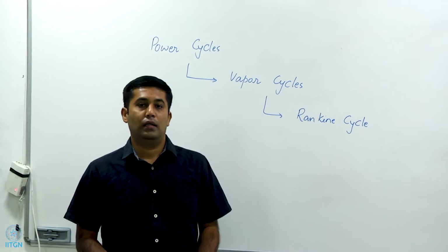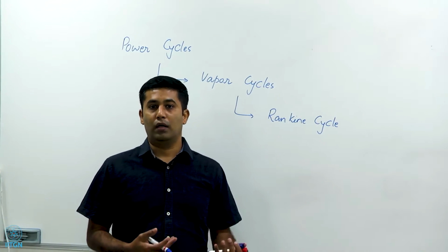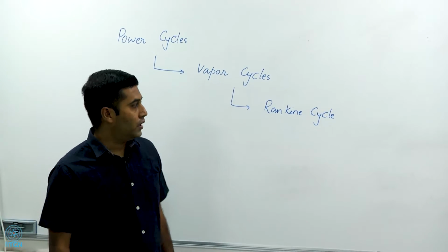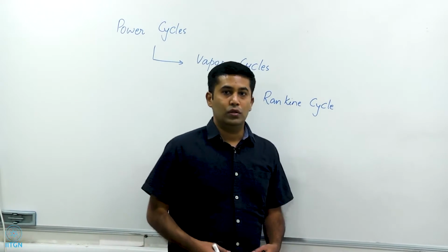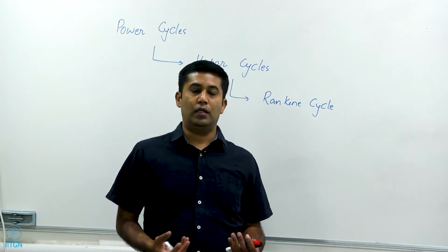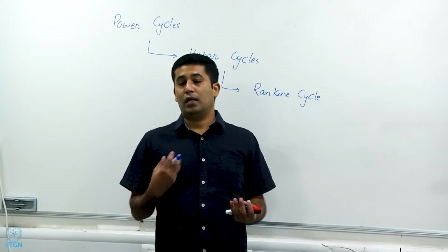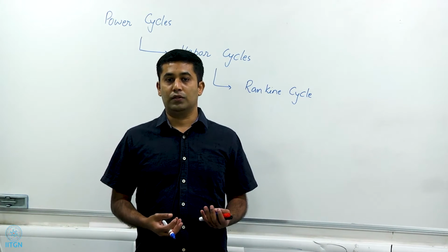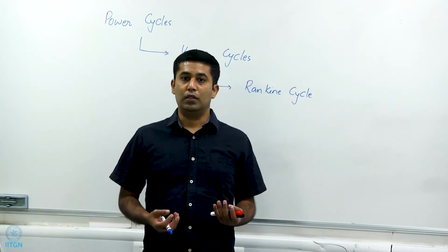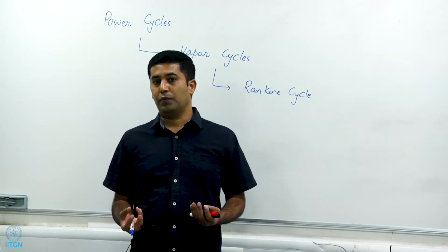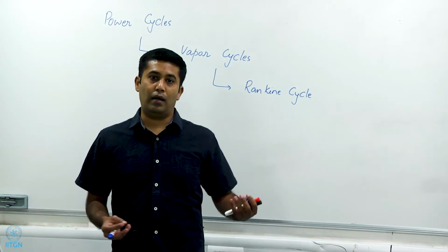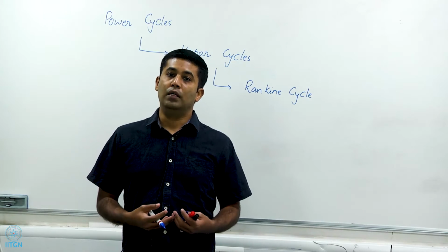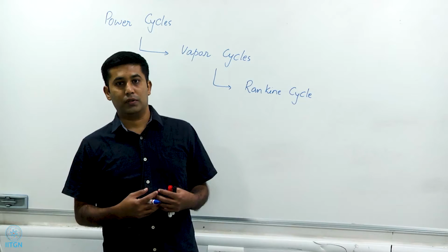But before we do that, we need to revisit some of the principles that we learned so far in this course. What are those principles? Those principles state that, for example, if I have to compress a fluid from a particular pressure to another given pressure, I would rather do it when it is a liquid than a vapor, because that would consume a lot less work than it would if I were to compress vapor instead. And if I were to expand, then I would rather expand a vapor because that gives me a lot more work than the expansion of a liquid would give me. So these are the two principles that are used.